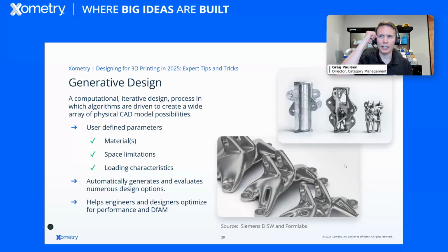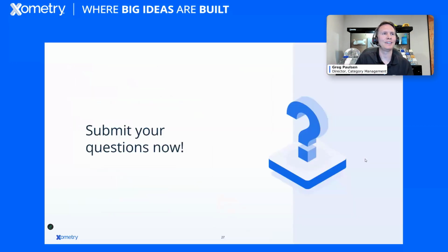Yeah, absolutely. And what's great is that list is getting longer every year because I'm a big proponent of generative design, but accessibility is always a challenge. Right now, it's very much seasoned engineers who have access to these types of tools. But like Matt mentioned, Fusion has a generative add-on now. It costs something, but it still gives you some really cool results. It's that cool idea of saying, here's the thing I wanted to do, here are the areas it needs to attach to, here are my keep-away zones, make it. It's like prompt engineering for a 3D space.